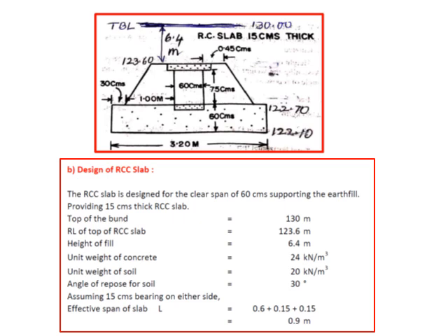This is the barrel, where the side wall is of trapezoidal shape, which is here, and this is the barrel, which is 60 centimeters by 75 centimeters high. We have provided a 60 centimeters thick concrete bed. You know that the sill of the barrel is kept at the canal bed level, which is 122.7.